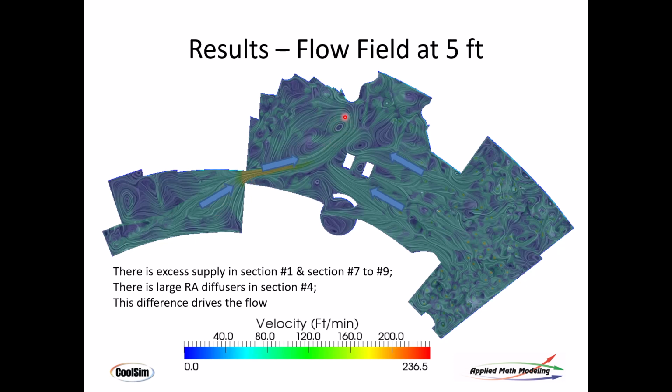And then you see these eddies, these currents, small vortices in the room, quite a few of them. This is where smoke will accumulate and get pretty thick because that's a low pressure area in the center, and that'll cause accumulation of smoke density, and that will cause issues. It's a little better over here. This is a better representation because the eddies are smaller and they're more distributed. But here you've got a couple of big ones, and that's going to cause issues.